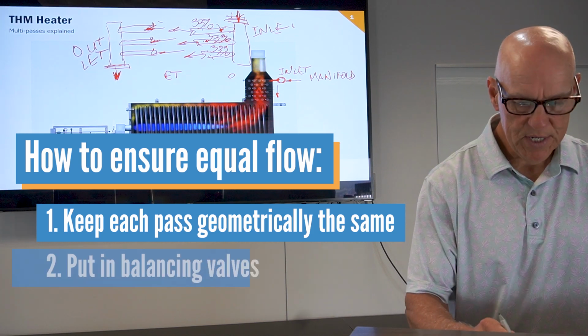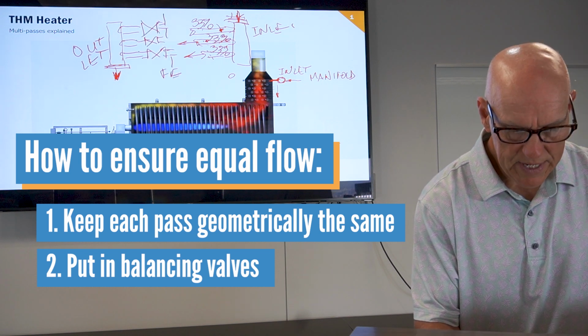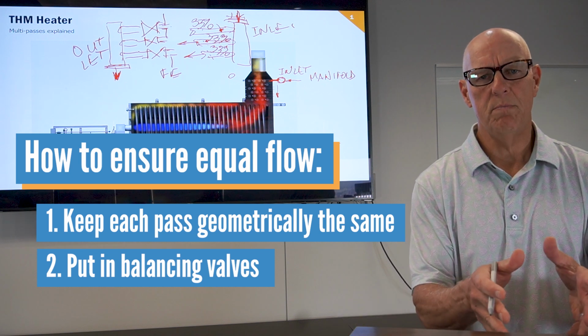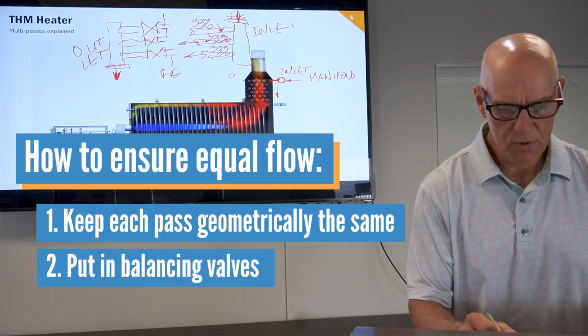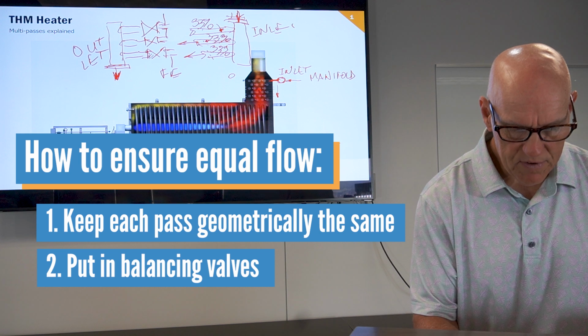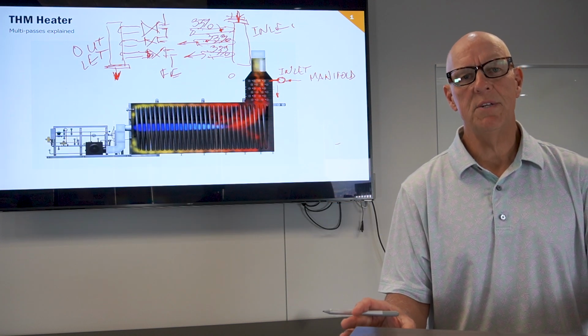Another step that you can take is you can put in balancing valves. So I'm going to measure the flow in each pass, and then when I find out, hey, this pass is flowing more than the other pass, I'm going to come up here and I'm going to pinch back on this valve a little bit and balance out that flow. So those are called balancing valves.